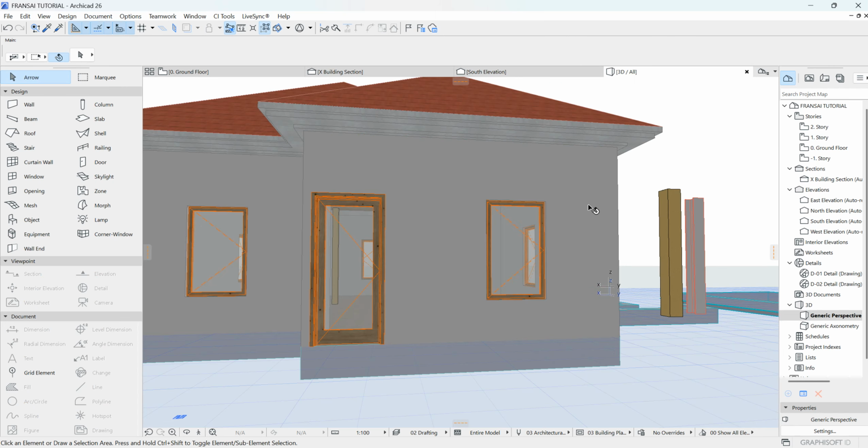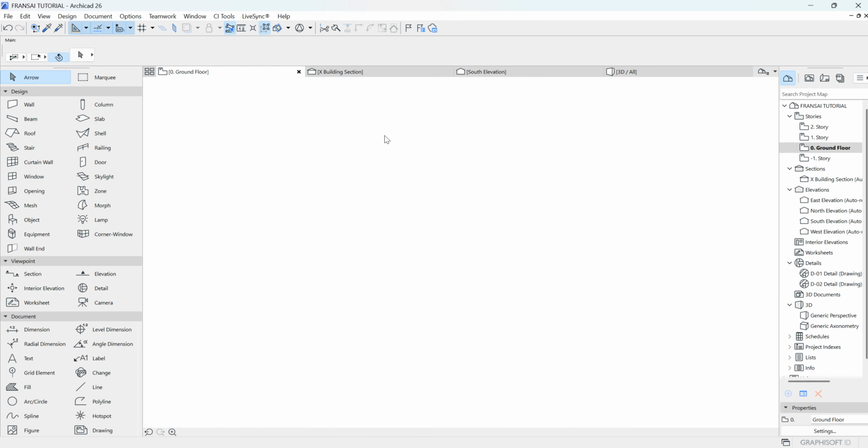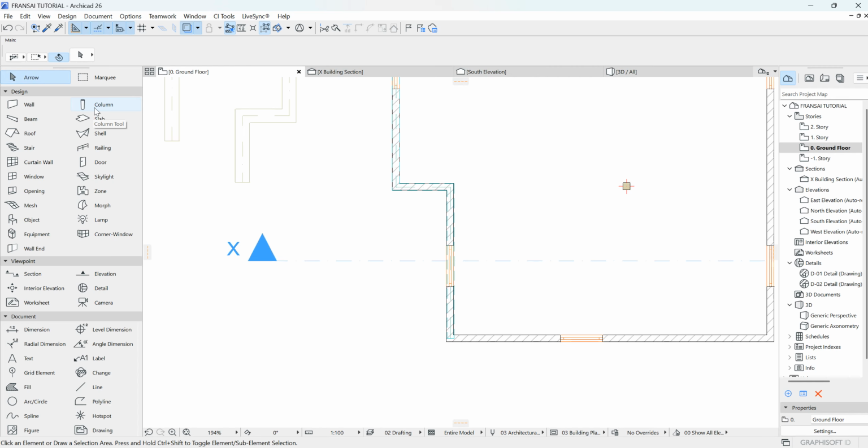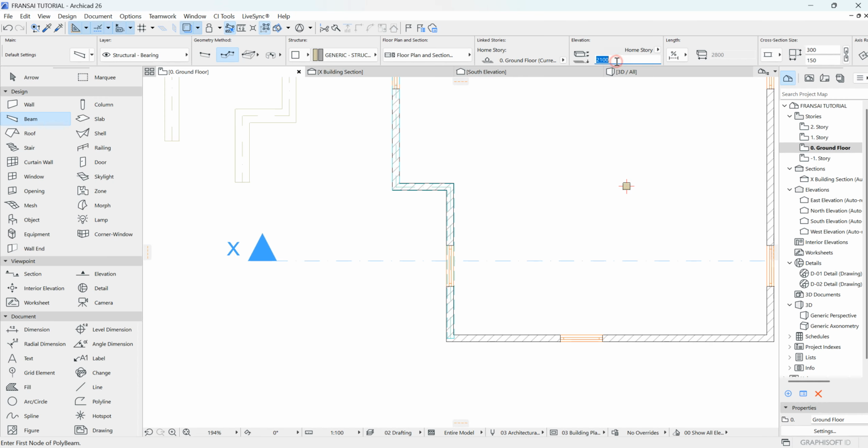It's hiding inside the wall. So it's just a total waste of time if you are drawing it. What most people use it for is, let me click on it. Here's the beam tool. Let me make it 2.4 because of the experience we had the last time. Same size, 300 high, then 150 wide.